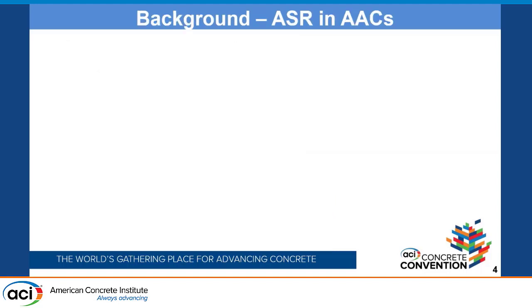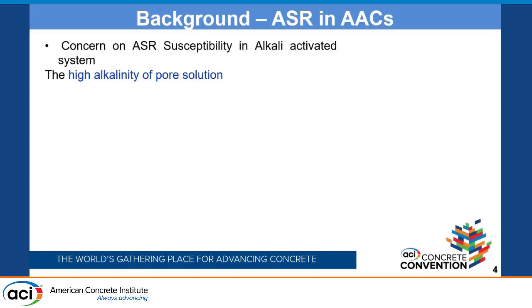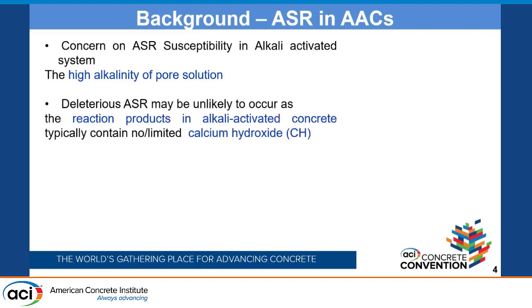So now coming to the problem of alkali-silica reaction, which is one of the key degradation mechanisms in any concrete if you use reactive aggregates. Alkali-silica reaction in alkali-activated concretes becomes a concern because of the high alkalinity of the pore solution, which is derived from the high pH alkaline solutions used for activation.